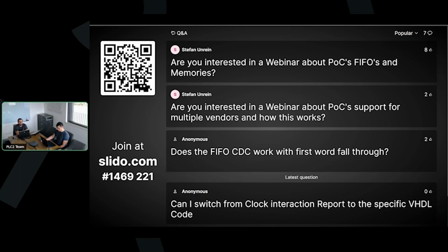It's a different picture when it comes to FIFOs, so the CDC FIFO that has resets. But be careful with resetting. If the receiving side resets, you also need to inform the sending side that you killed the data that it thinks might be inside of the FIFO. It's quite complicated.